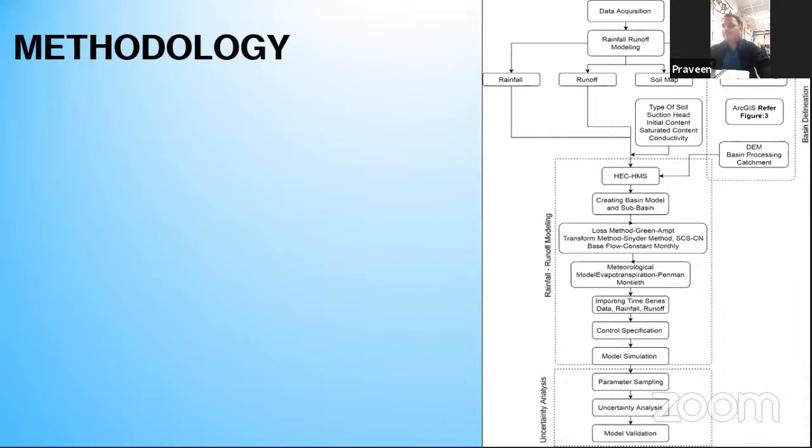That's not a problem. The problem here is how you can fit the data or the model parameters which will give a reliable output, right? Suppose you have certain discharge data, and whenever you give a rainfall, there should be a relation between these two parameters, but it won't match in general. Why? Because there are so many other parameters governing.